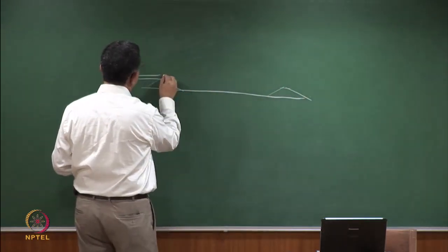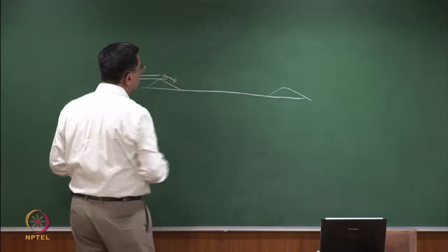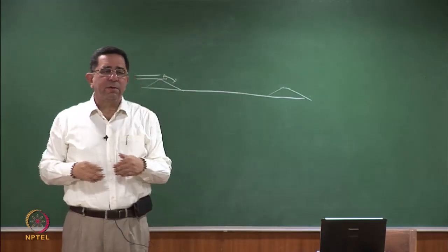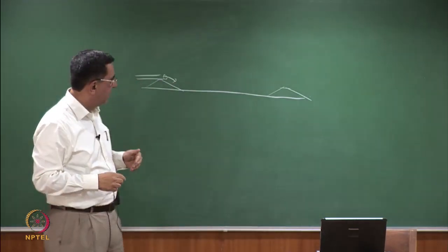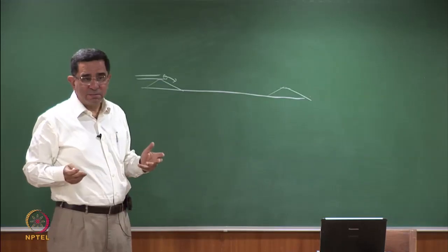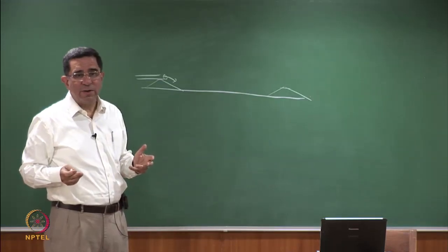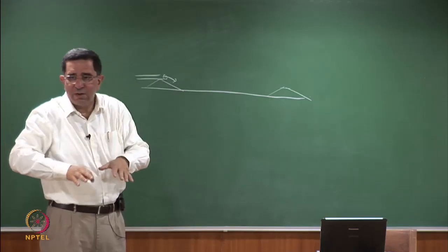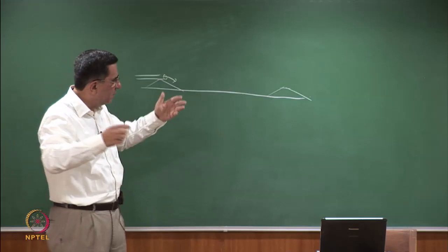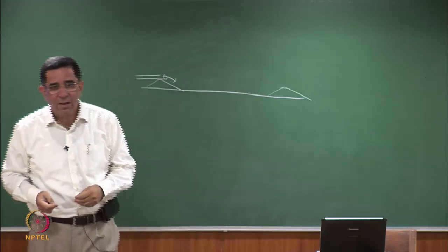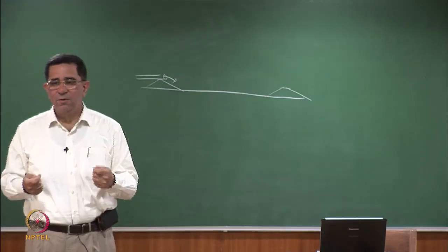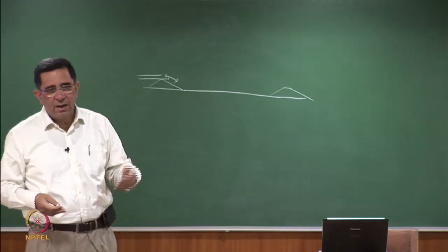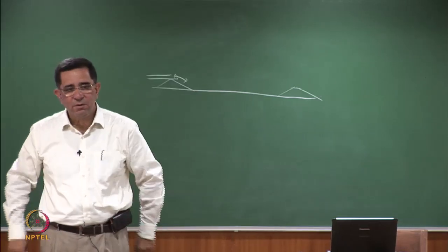I'm just looking at the inflow. So I'm throwing in my slurry into a ring impoundment, and I want to take out the supernatant water, or the water which is at the top after the solids have settled down. So give me an arrangement. How will you do that? How will you take out the clear water from the top? When it's coming in, it's in the form of a slurry, and how will you take out the clear water from the top?